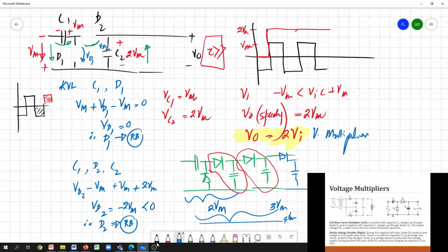For those circuits, the steady state output would be exactly similar to the other cases, but during the transient process you will observe different voltages among these capacitors, and the switching of D1 and D2 may be different. Ultimately you can reach the same output for different diode capacitor arrangements.